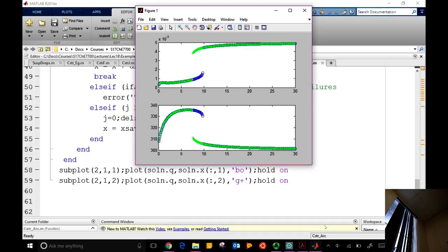Okay? But it was not exact. It becomes exactly singular only at a particular value of q. And I don't hit that value because I don't know what that value is. So to find that value, what I need to do is impose the Jacobian eigenvalue to be 0. And I will show that algorithm in the next class. That is what is called the limit point, finding the limit point.